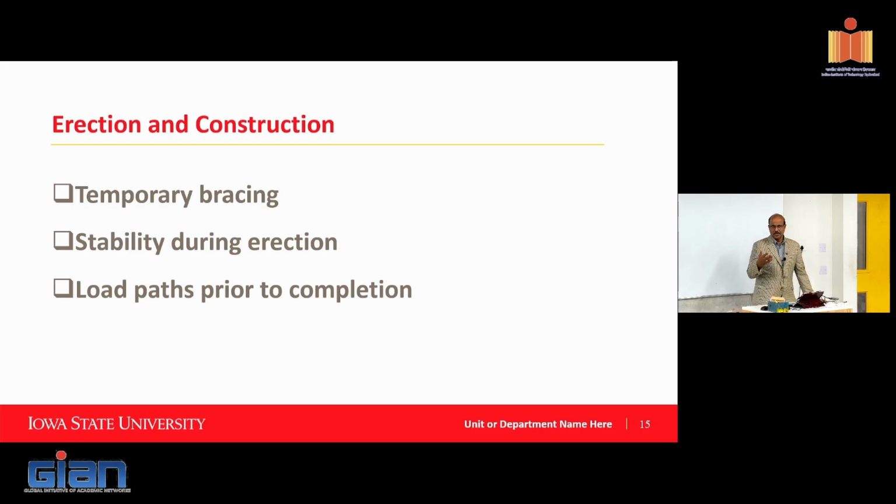I talked about the fact that all of the grouting and welding takes place after you assemble the entire structure. That's a typical process because different crews get involved. Also, as you keep building, the building settles because of the gravity loads and things like that. So they want to allow all of that to take place before they do the grouting or welding.